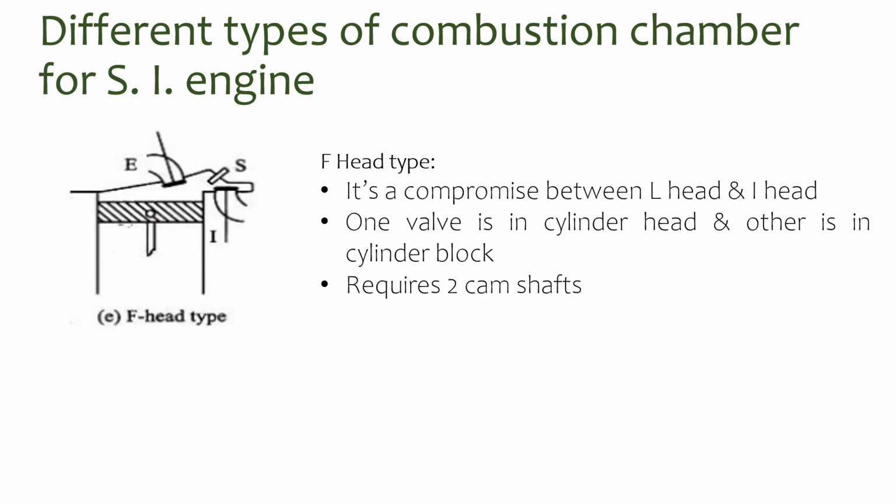The last one is known as the F-head type. It is a compromise between the L-head and I-head. One valve is in the cylinder head and the other is in the cylinder block. It requires two camshafts.